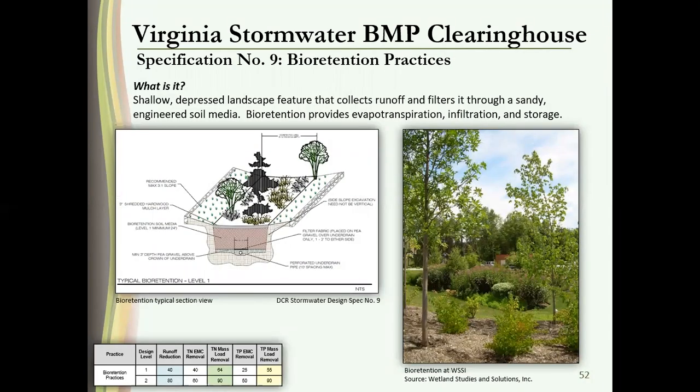Bioretention. Bioretention is kind of a big umbrella word. It encompasses a lot of different kinds of practices, but it's a way of getting your water... Yeah, we can't get it all the way into the ground, but we're going to give it sort of fake soil and have it percolate through that fake soil as much as we can. Again, depending on how deep your soil is and how much rainwater it's getting, you can get a lot of treatment out of a level 2 bioretention facility.